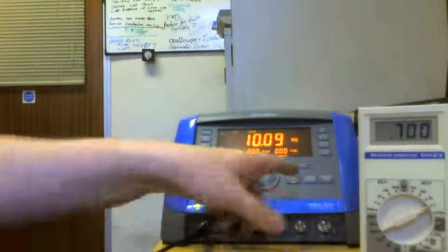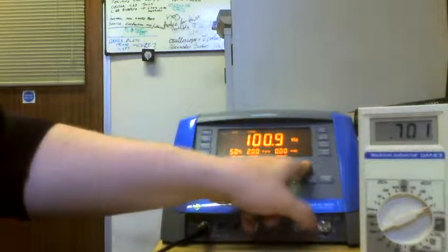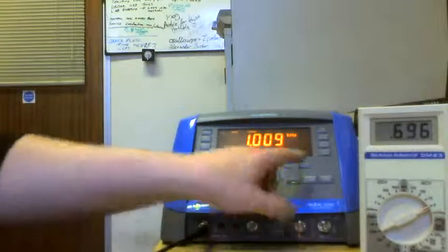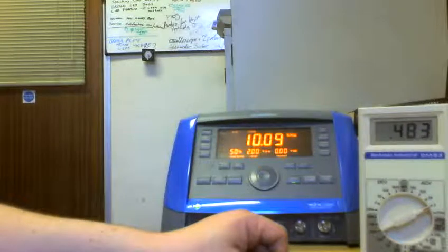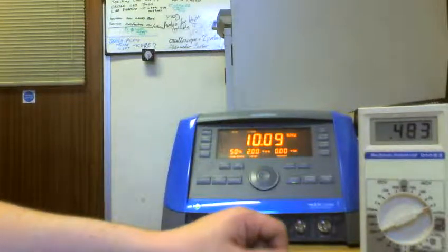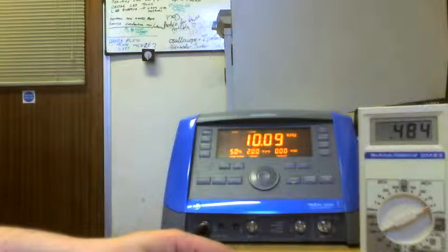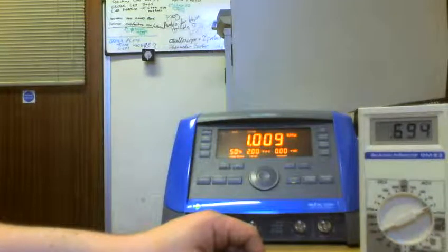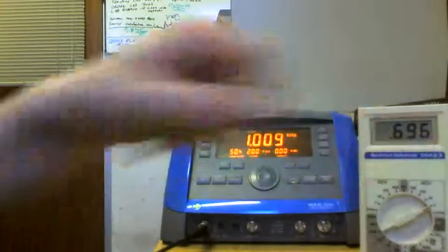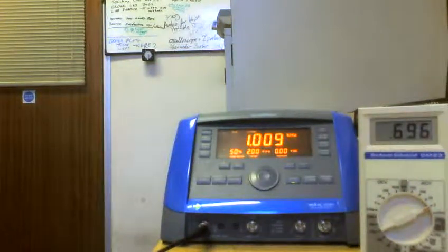That's low frequencies; high frequencies, 100 hertz, fine. Kilohertz, still fine. 10 kilohertz, now it almost drops by a quarter. 484 millivolts it's reading when it should be reading about 700, so obviously it's pretty bad. So let's go back a range, back to 1 kilohertz, because that was okay. And you can already see it's dropped down a bit, because it was 0.699.